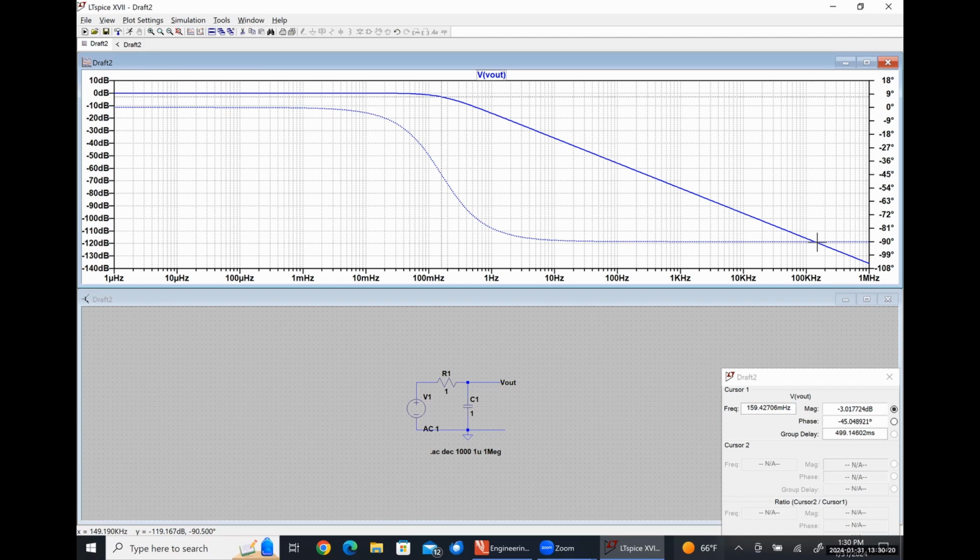Okay. We can also see, if we look at this graph, that for very low frequencies, the phase angle of our signal is unchanged. It's not until we start getting to pretty much within a decade of our corner frequency where our phase angle starts to change. At exactly our corner frequency, our phase angle is -45 degrees. And then about a decade beyond our corner frequency, we see that our phase angle settles to -90 degrees, okay? Which is effectively what we would expect for a first order response. So let's talk about that just really quickly.